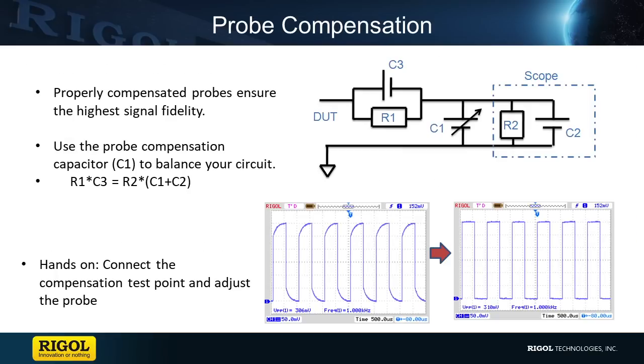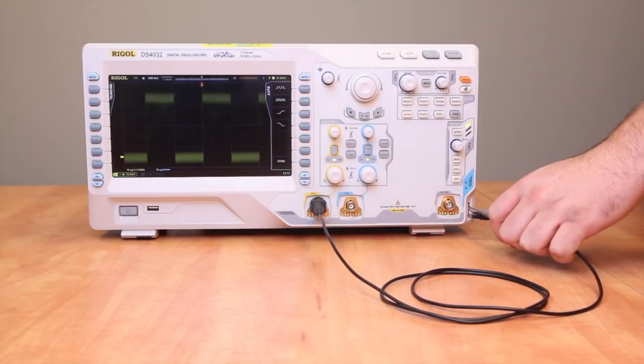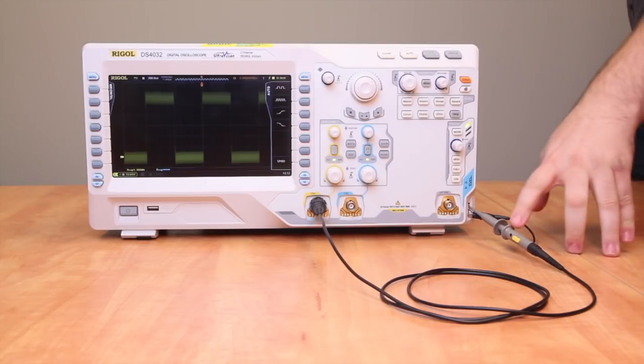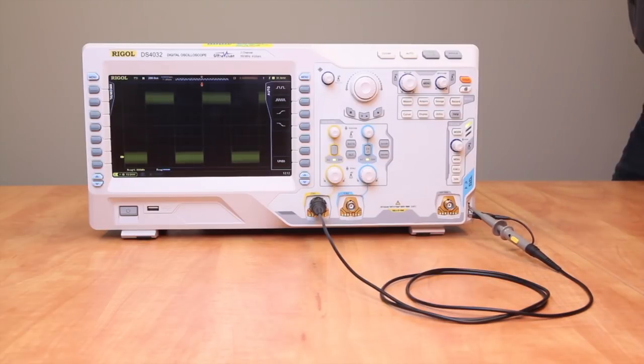And then one thing that's always worth doing once in a while on a scope is to look at the probe compensation point. All the scopes you'll see have a little probe comp port here on the front, and what you should always see is this sort of square wave, right? And there's a little screw mount in the probe itself to make that more square. It changes the capacitance to even it out.